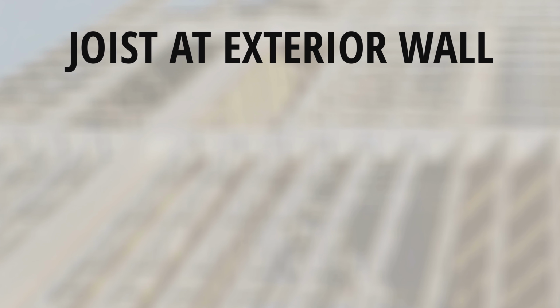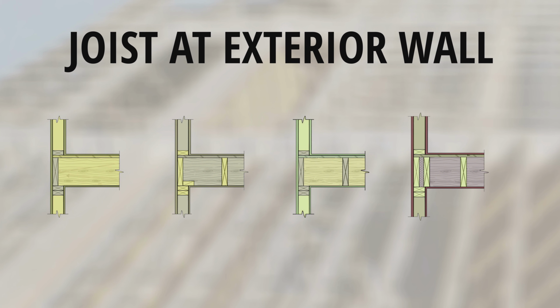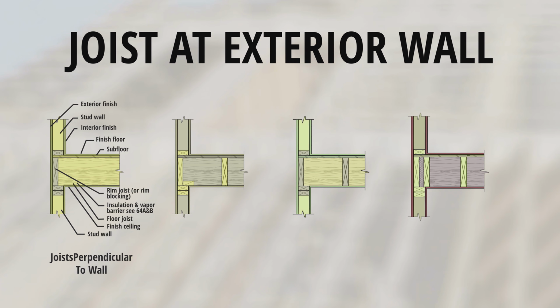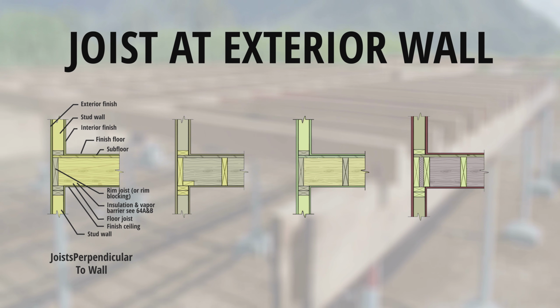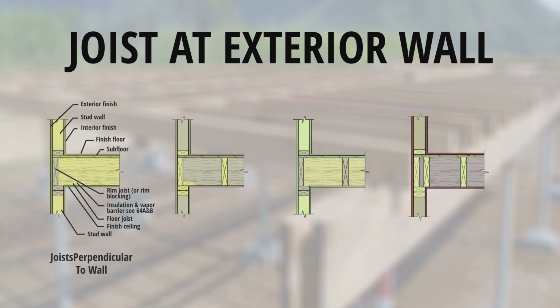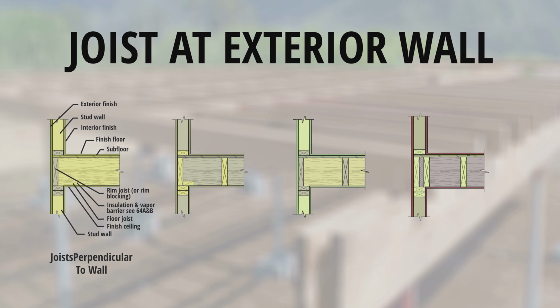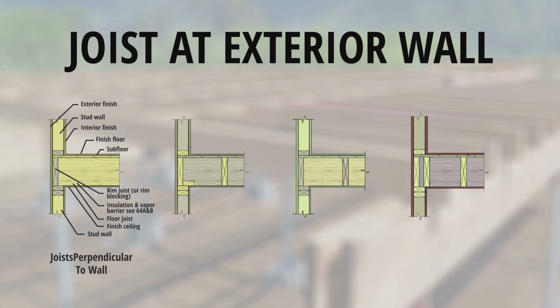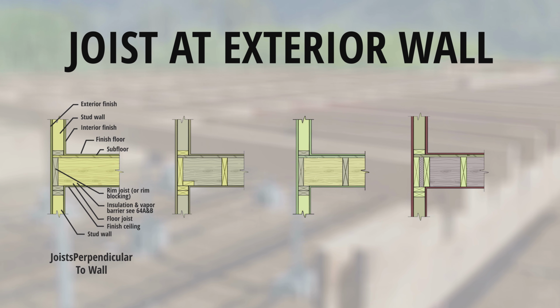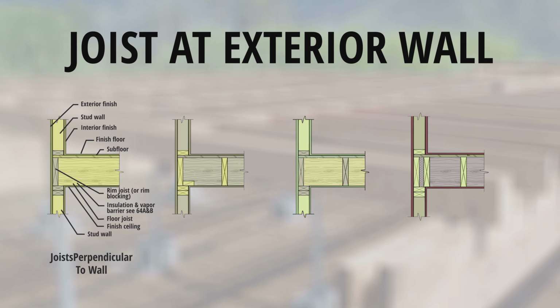Joist at exterior wall. A: Joist perpendicular to wall. Exterior finish. Stud wall. Interior finish. Finished floor. Subfloor. Rim joist or rim blocking. Insulation and vapor barrier. Floor joist. Finished ceiling, stud wall.